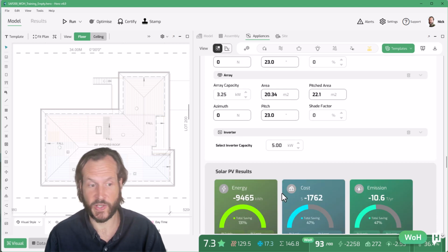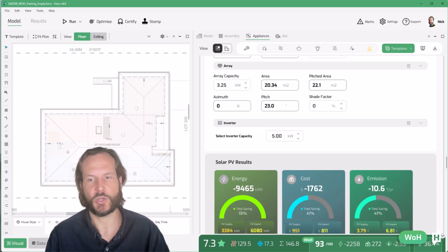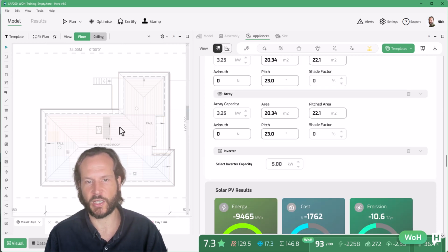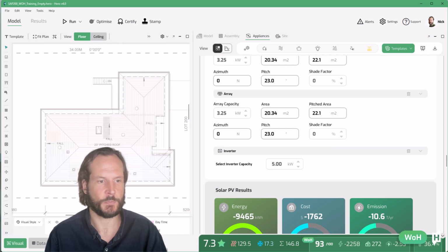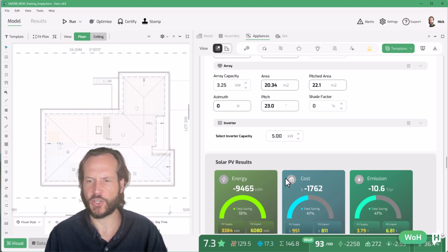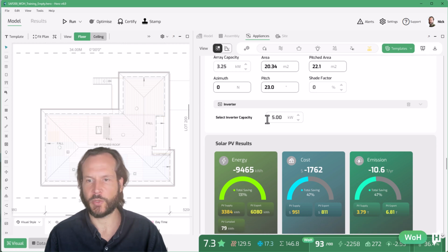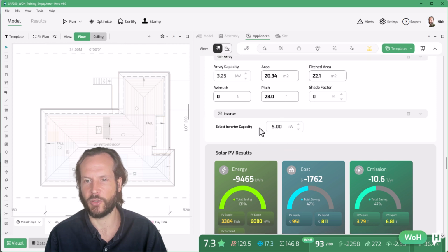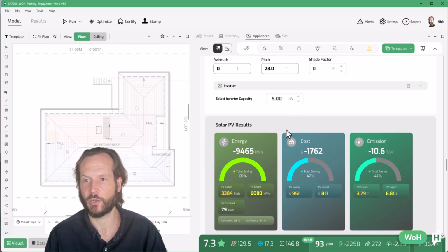They have varying levels of oversizing capacity that they warrant. Oversizing is usually very sensible to do in a solar system because a lot of the time you're not producing anywhere near that peak, particularly when you have multiple orientations, and so you can more economically size this inverter. And you can demonstrate that pretty easily where we see here, despite producing around 9,500 kilowatt hours of electricity, there's only about 80 kilowatt hours of generation that's curtailed on this 6.5 on a 5 kilowatt inverter.